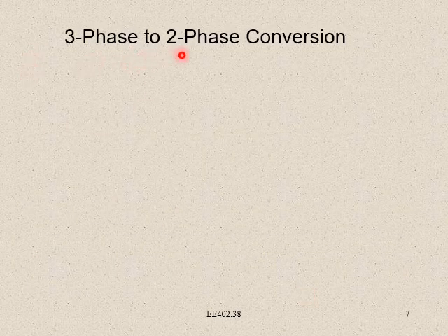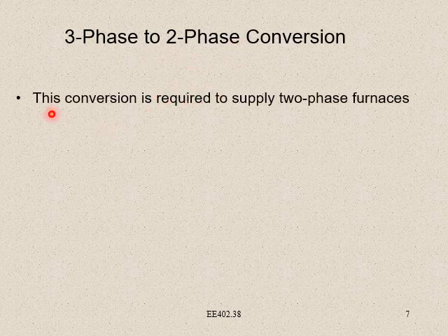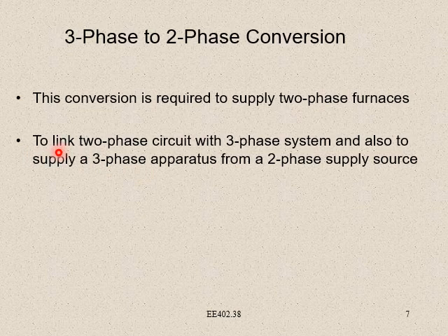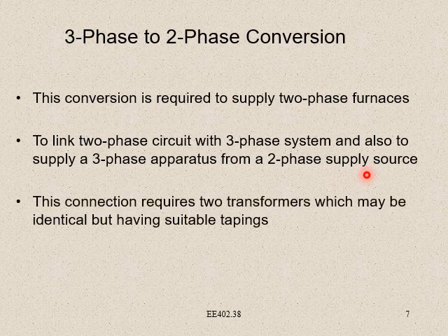Now three-phase to two-phase conversion. This conversion is required to supply two-phase furnaces, to link a two-phase circuit with a three-phase system, and also to supply a three-phase apparatus from a two-phase supply source.